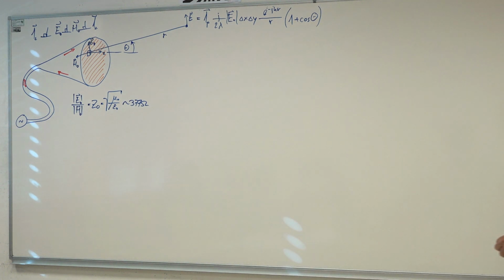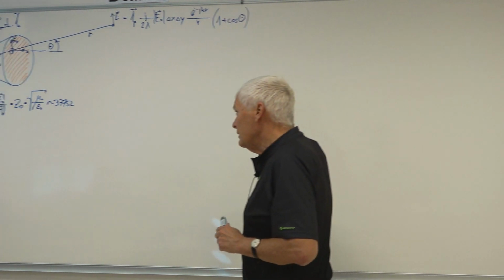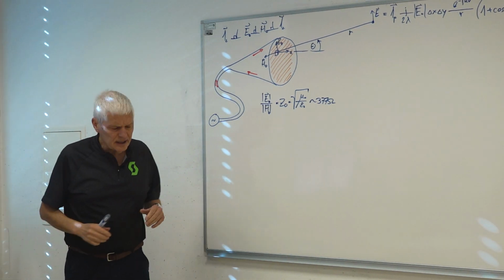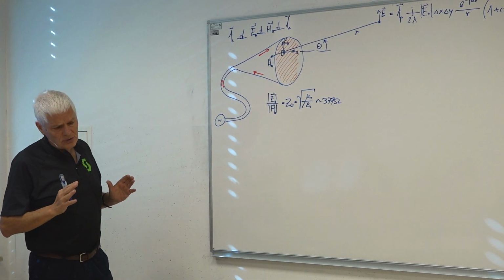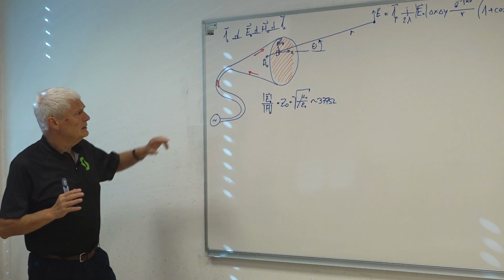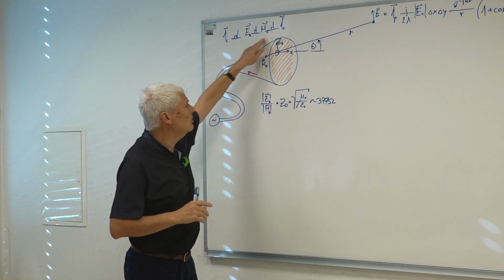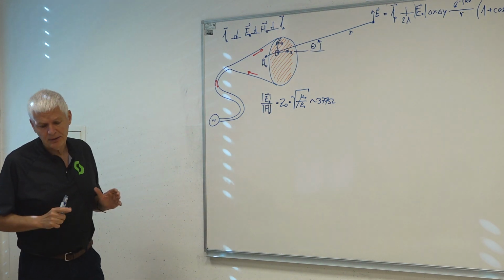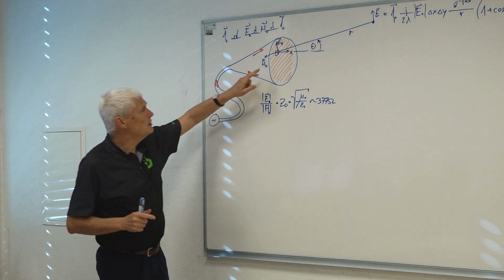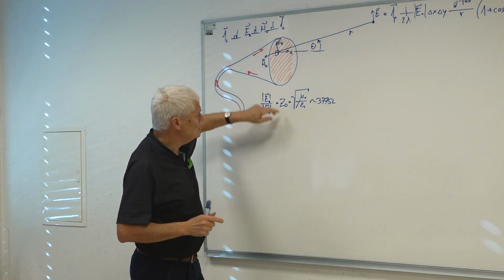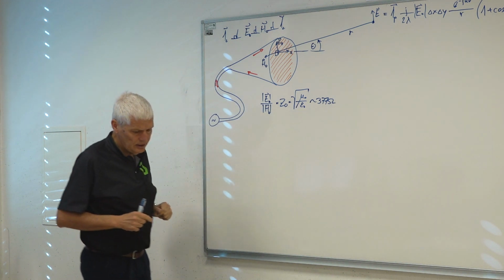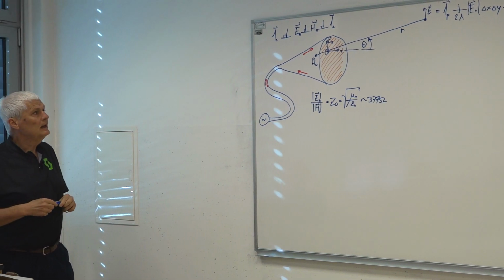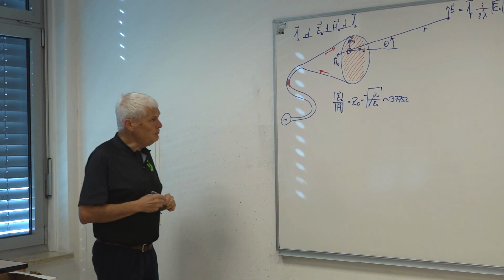So this was the way to analyze complicated antennas, thinking that the field in a large aperture is almost a wave in free space. That this thing holds and this thing holds. This is not exactly true. But the larger the aperture, the better the approximation. The larger the aperture, the closer we are to this approximation with the plane wave field in infinite space. So this is not such a bad idea.